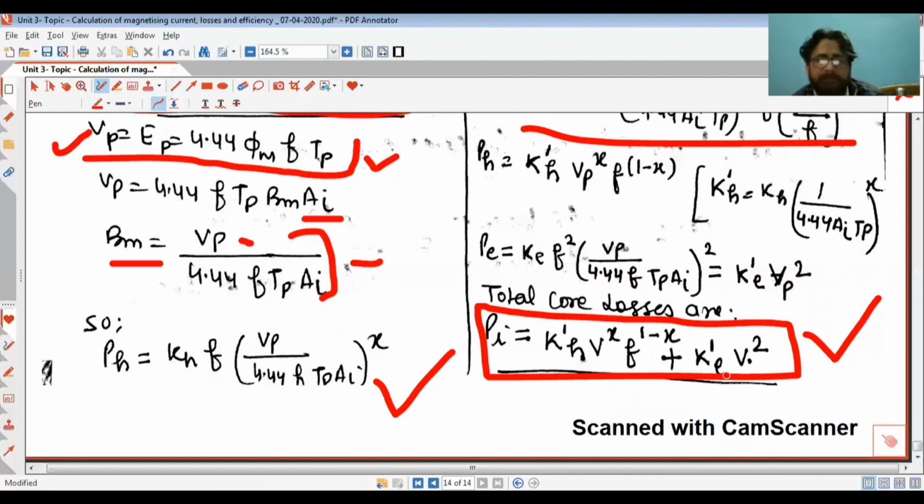So in this chapter we have studied the operating characteristics, which include the calculation of the magnetizing current, and the calculation of the effective component of no load current, which is responsible for the iron losses, and we have also seen the equation for iron losses. Then we have studied the resistances to find out the total copper losses. So iron losses covered, copper losses covered. Similarly, efficiency is covered, and voltage regulation and reactance are also covered. So this is it for this lecture, and here our syllabus for unit number 4 is complete. Thank you so much.